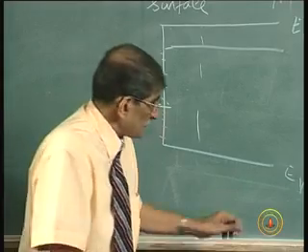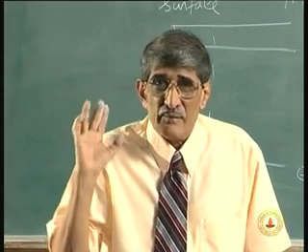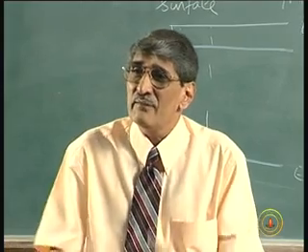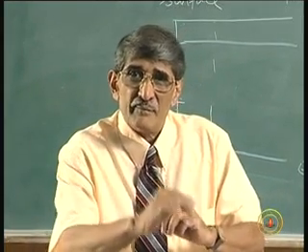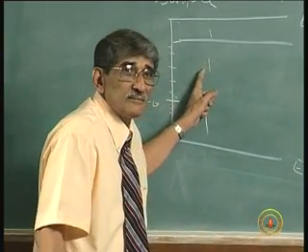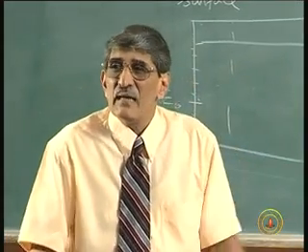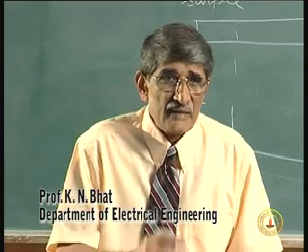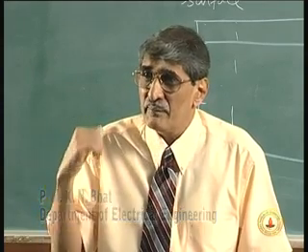I think I will discuss this next lecture, because this is a very important concept. What emerges from here is, even if you take a free semiconductor surface, do not put any metal, that will have a depleted surface, because these electrons will have to be supplied from this region. So, the entire energy band diagram will bend. Okay. That aspect is a very interesting aspect, which hurts the MESFET. When you make the MESFET in enhancement mode, that is the difficulty people have. So, you will have a depleted surface.